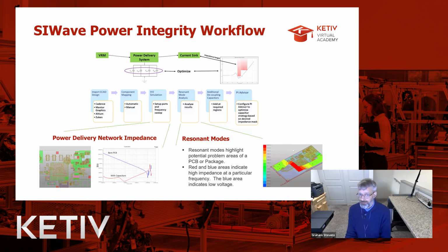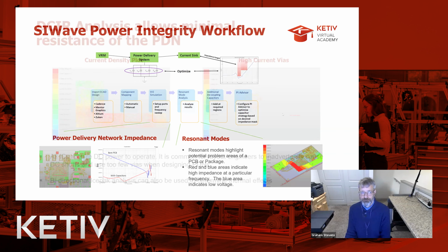And a typical SI Wave power integrity workflow looks like this, where you import your ECAD design, do your component mapping, set up an SYZ simulation to look at impedance for the power delivery network. You can see here's a bare PCB, and with capacitors, you say we're doing design to improve the impedance there. Look at your resonant modes. And then there's something called a PI advisor to help you with optimizing capacitor strategy based on your desired impedance mask. So all of these are different power integrity analyses you can do in SI Wave.